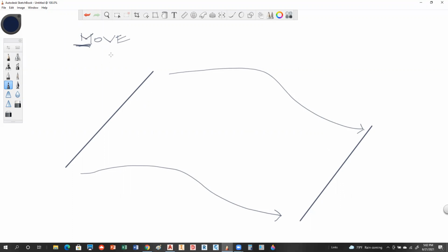So when that happens, move is actually doing what's called translating. So we call this process a translation. So move will do what's called a translation, okay? So what it's really doing is giving you a displacement vector in delta y and delta x to each point on those respective endpoints. Also, if this line has, say, an angle of 60 degrees with respect to X, that'll also be 60. If this line is 5 inches long, this will still be 5 inches as well, okay?